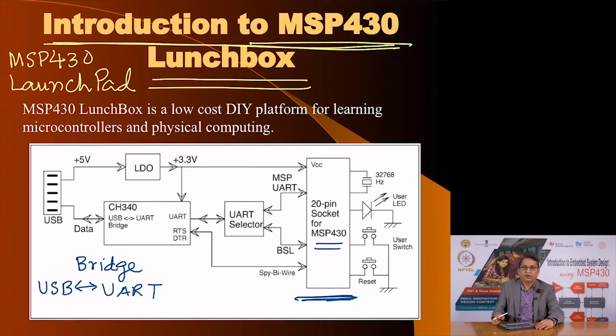Now, there are several mechanisms to achieve this bridge functionality, and we have used an IC called CH340. This is a commonly available bridge integrated circuit. On one side it connects to the USB, and on the other side it has the UART functions, and apart from that it has 2